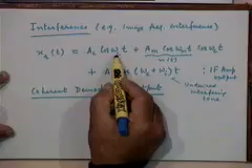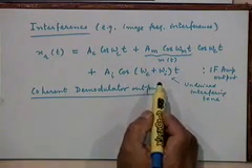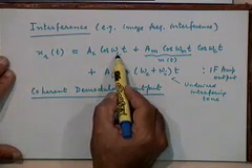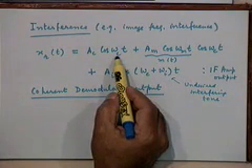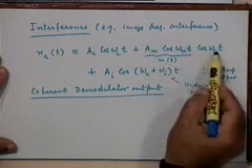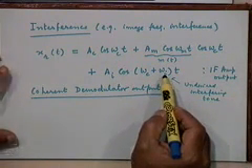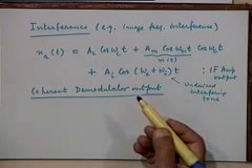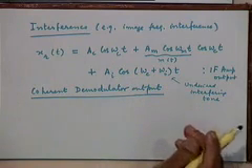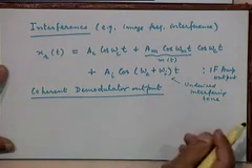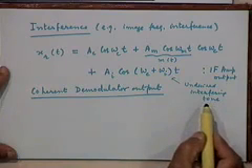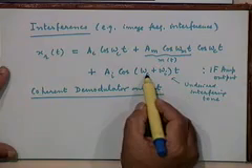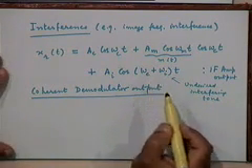No, think of this omega_c as omega_IF, right? Normally at the output of the IF filter you would have only got a carrier at the IF frequency, and both here as well as here. But along with that you are also getting a close-by tone which the IF filter cannot reject, right? So this interfering tone is close to that omega_IF, and therefore it cannot be rejected.